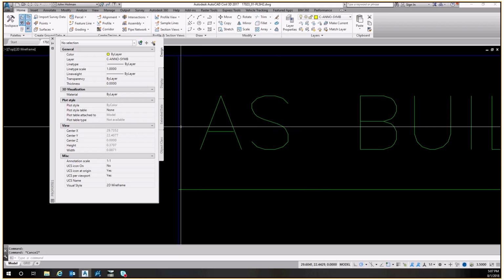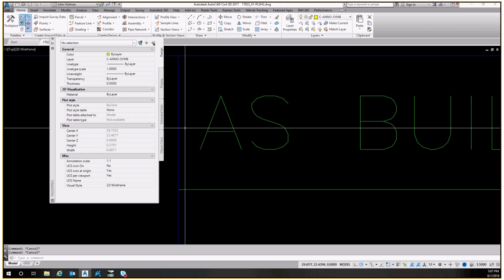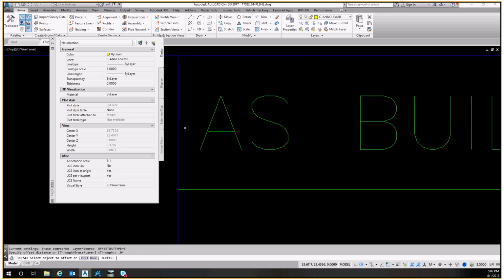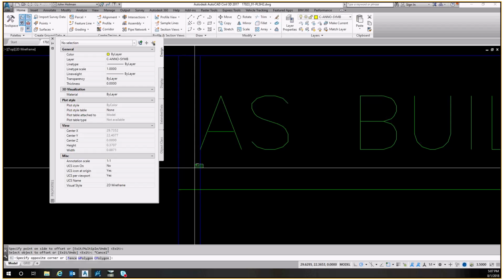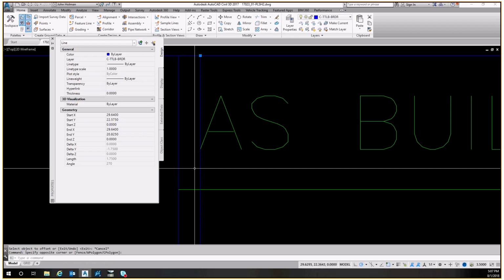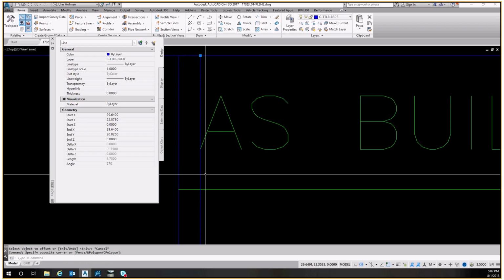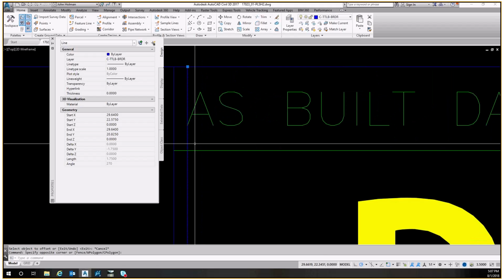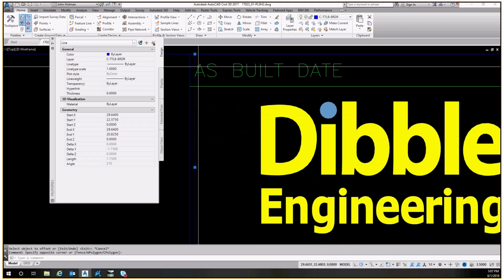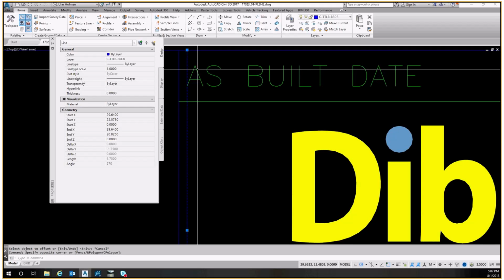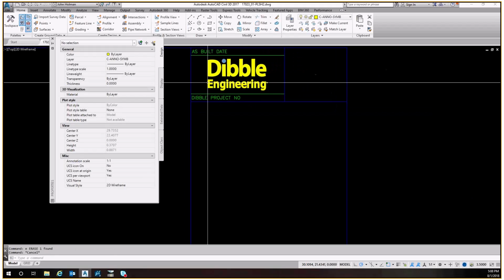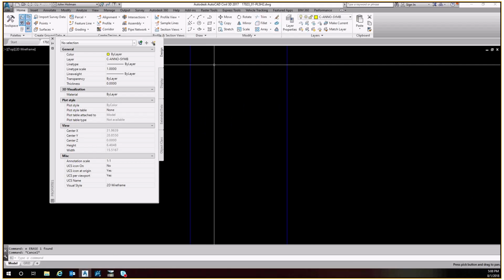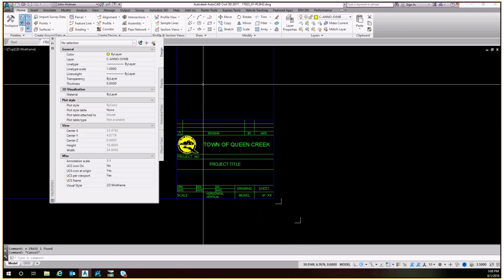0.04 inches away from this blue line. And I'll go ahead and show that by offsetting that line right now, 0.04. The reason why 0.04 is because that just is a good dimension that works well for spacing, not creating blotchy drawings, but still tight enough that you're not wasting too much space there to the left of that text. So that text block right there is placed at a good spot, and actually this one is as well. So the top guys are good in their horizontal spacing. I know for a fact these bottom ones are not, but we'll get to those later because we'll handle this